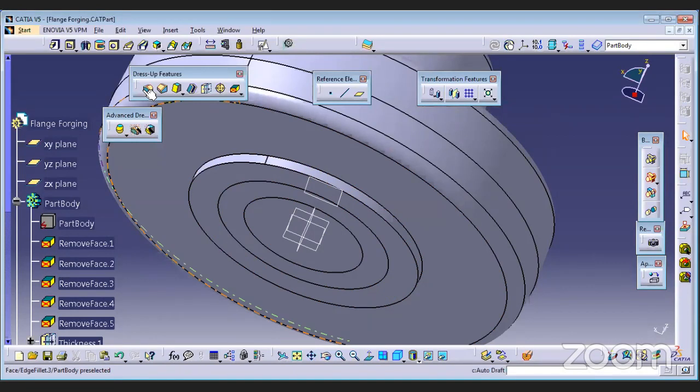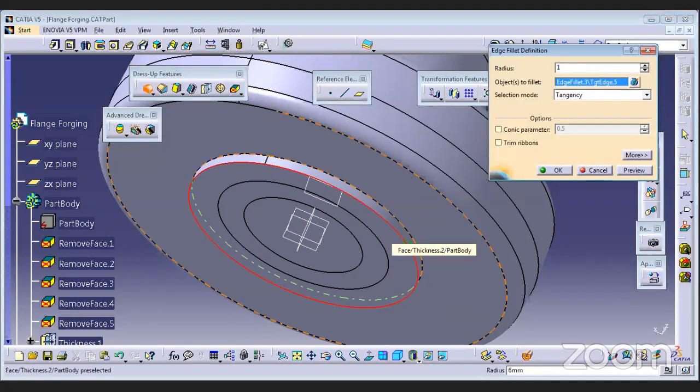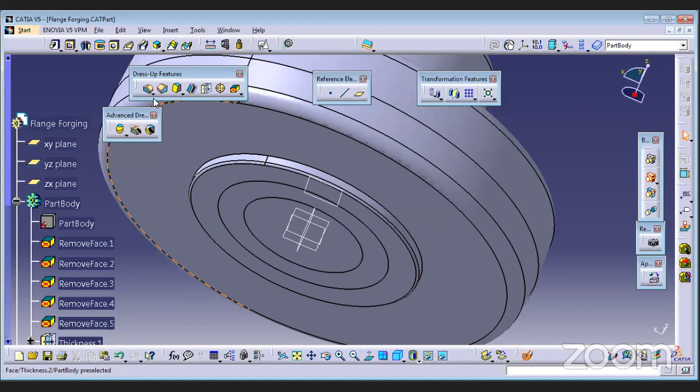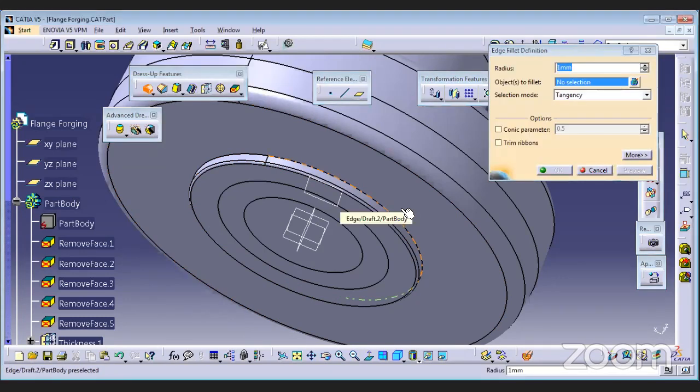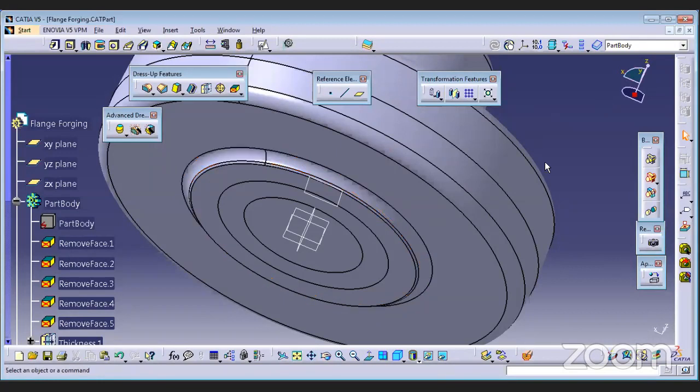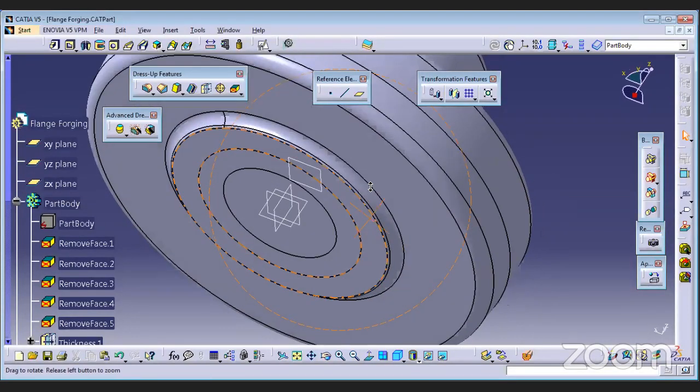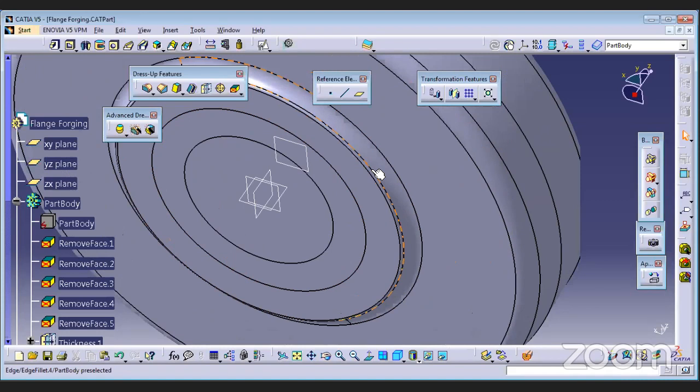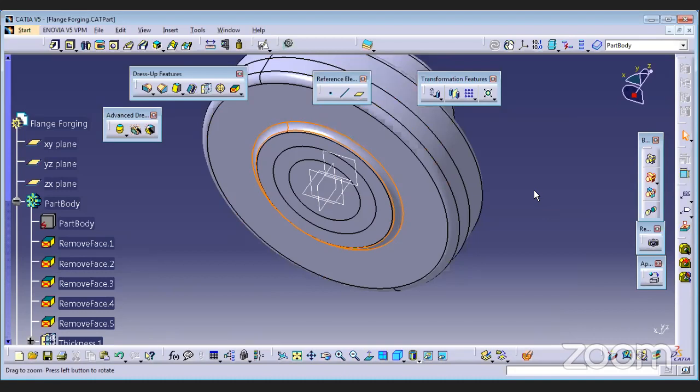So first apply this fillet of 1 mm. It is given as 1 mm, and then go for this fillet. So it's basic or very simple solution. Then it is possible because in this case we have extra space available. Okay, so here after applying fillet at this edge, we have extra space and we can apply fillet of 5 mm easily.